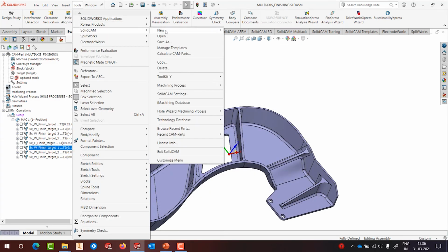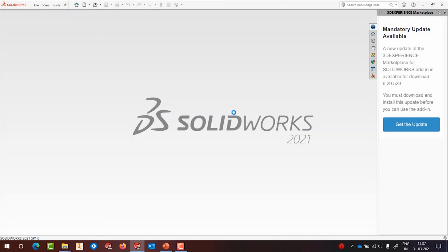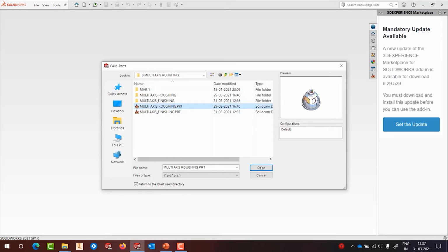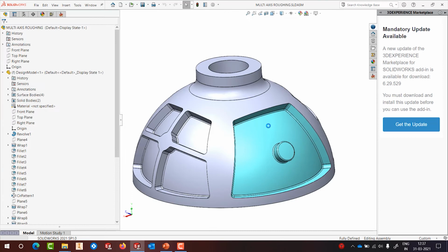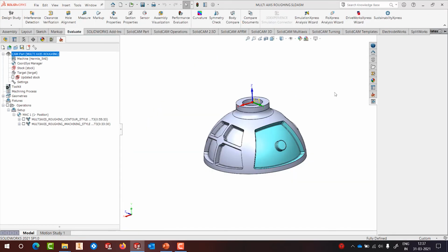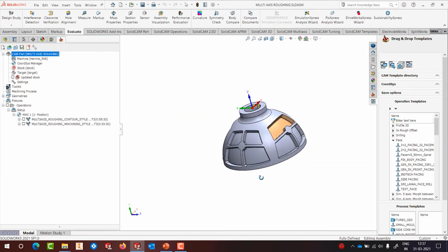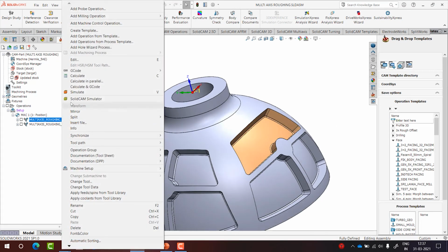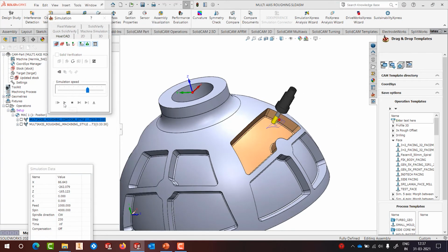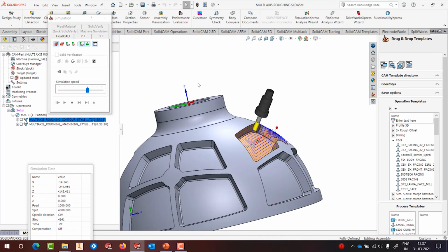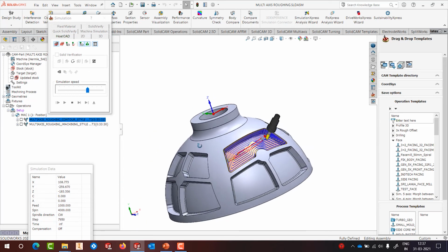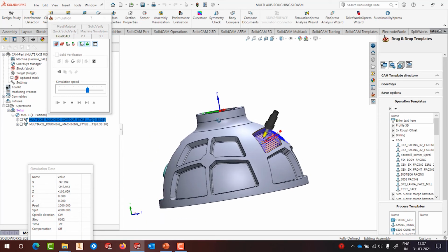To look at more parts in multi-axis machining, let's open this part where I can show you the tool path generated. For example, if I would like to cut this pocket here in multi-axis, I use what we call a contouring style. It creates a simple looking toolpath, as if somebody has done 3-axis roughing, but again in simultaneous 5-axis. It does the entire pocket machining as if a simple 3-axis machining toolpath was taken and wrapped around